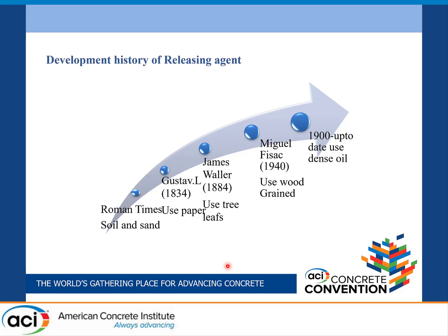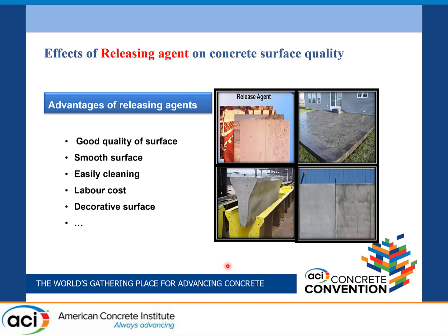So what is the effect of the releasing agent on concrete surface quality? Everything has some advantages and disadvantages. The advantage of the releasing agent is good surface quality: a smooth surface that is easily cleanable, decreased labor cost to clean the concrete surface, and a decorative surface.